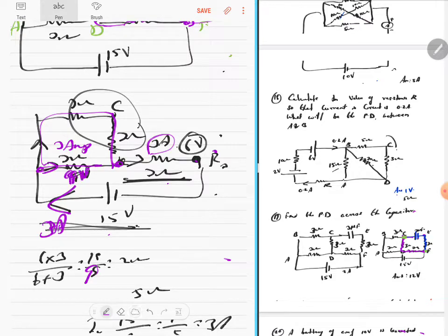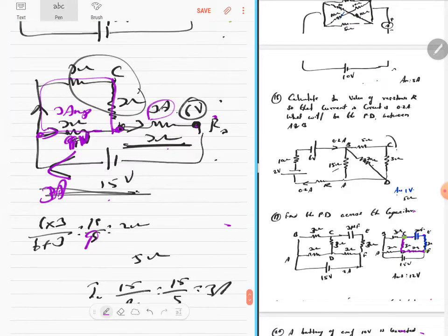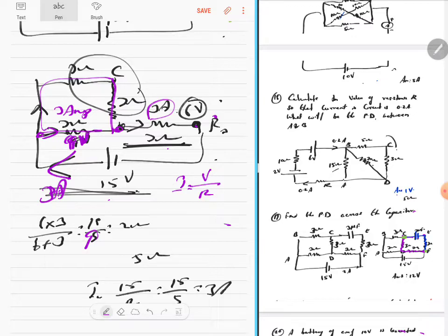You know the resistance here is 3, and what is the current? I is equal to V by R, 9 by 3. I am getting 3 amps. It can't be 3 amps there. Is it 3 ohms? This is not 6, it's 3 3s are 9 volt. I into R, 3 into 3 has to be 9. So therefore this side will be only 6 volt.